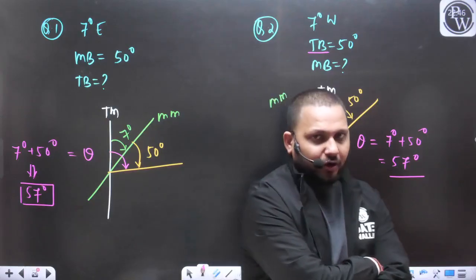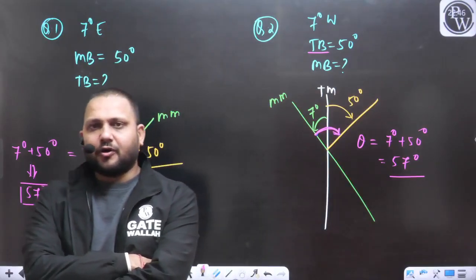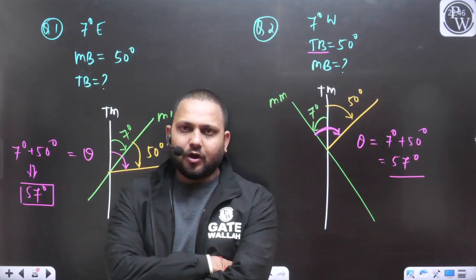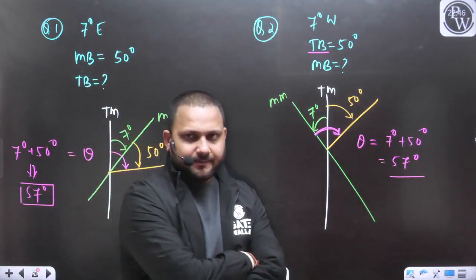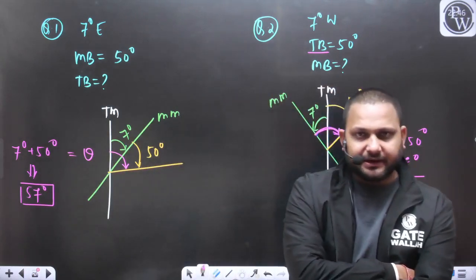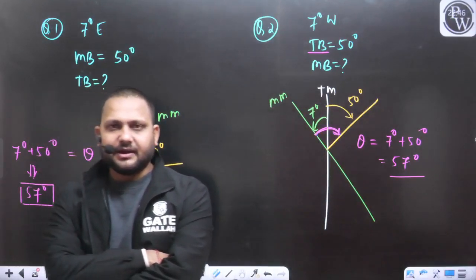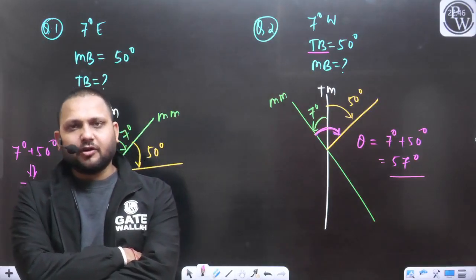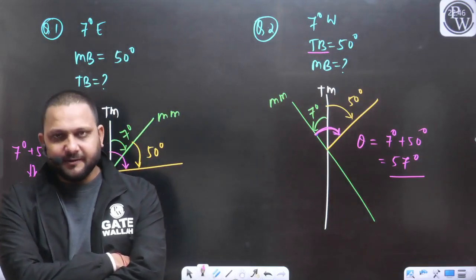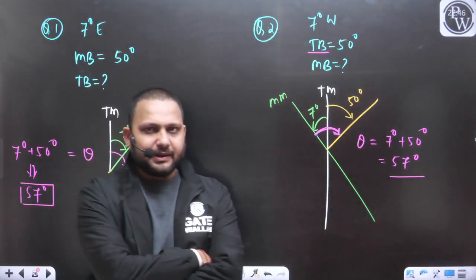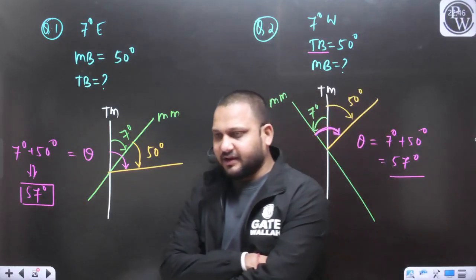So we have solved all these questions from the very basic concept. Again, I am repeating. If you want to solve these types of questions, you should know all the basic terms. What do you mean by the magnetic declination? The magnetic declination is the horizontal angle between the true meridian and magnetic meridian. The position of the true meridian will not change. The position of the magnetic meridian can vary. We have two types of declination, eastern declination and western declination.